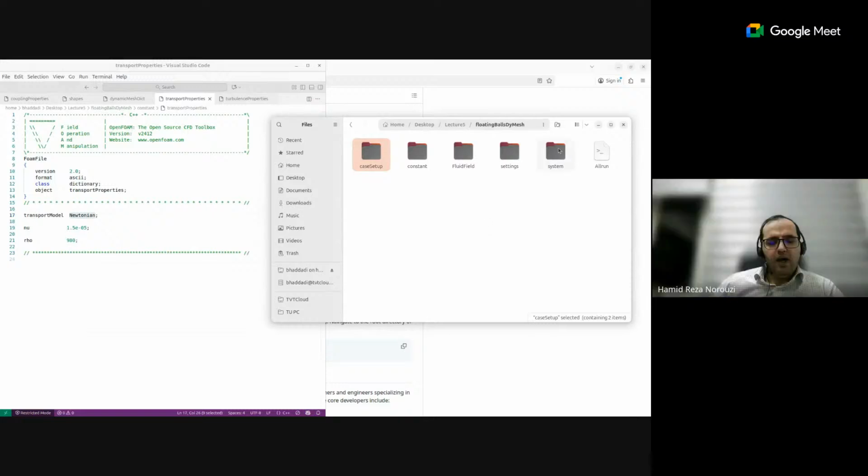Good. And let me just add one point here. With the resolved solver, I think it is already there, and you just need to change the viscosity model on the OpenFOAM side, because the solver resolves the fluid flow around the particles. So with the non-Newtonian fluid, you can also calculate the shear stress on the interface between the fluid and particle.